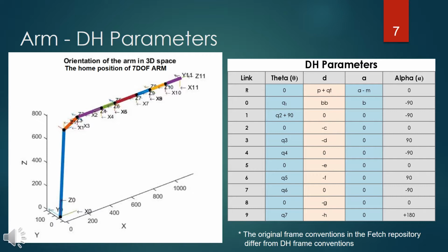We noticed that the Fetch robot frame convention wasn't according to the DH convention frame. So we changed the URDF to follow the DH convention, which helped us to compare our MATLAB results with the raw simulation.